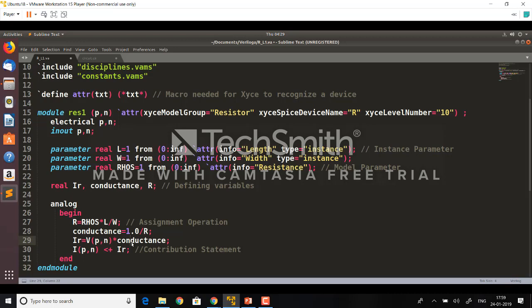No, yourself, because you know your device, right? You know what the physics of your device is. If it's a transistor, yes. Your device might not be a transistor. If it's a simple transistor but you do some tricks with it, for example you have two gates, or you bias the device such that the physics is not the same as normal transistor physics, then you need to include that physics in your model, in your code. If it's a normal transistor action, you can simply use any transistor model.